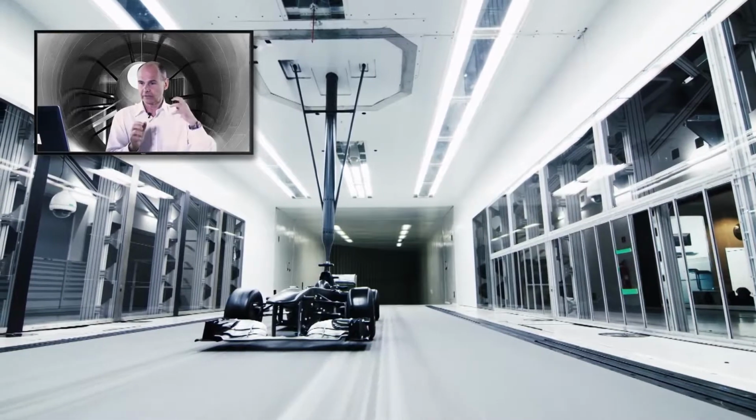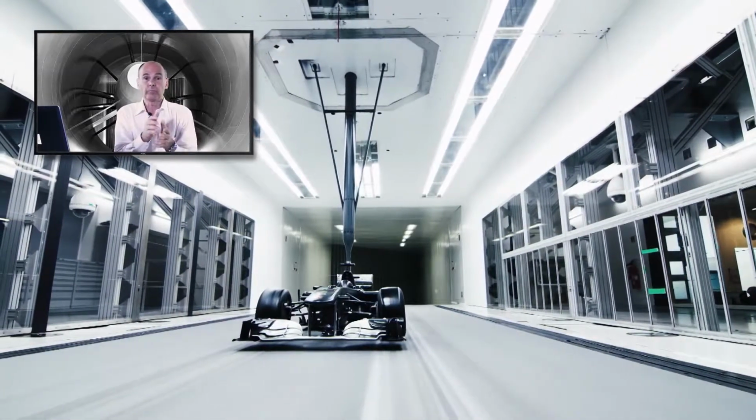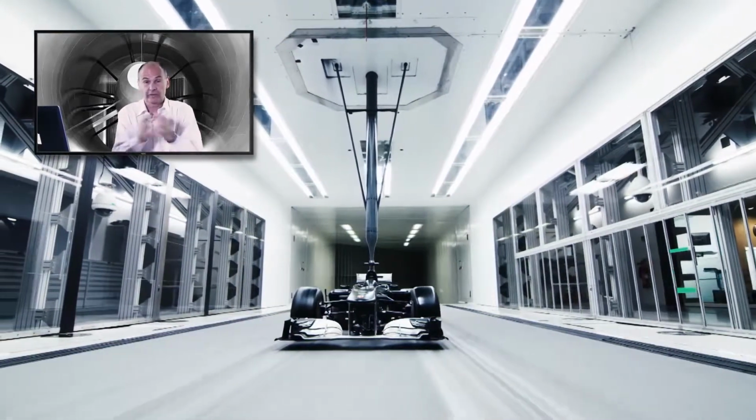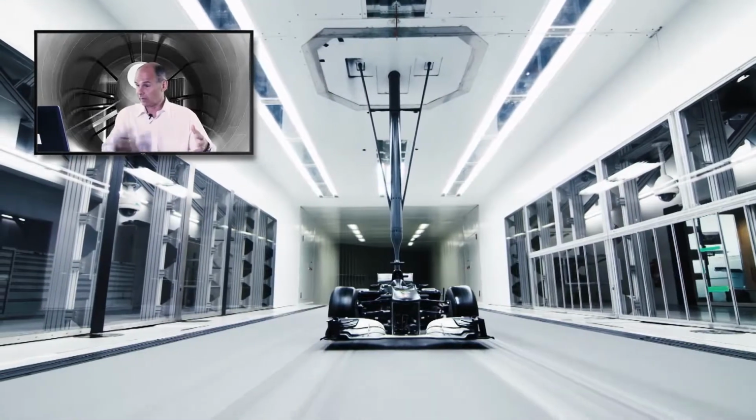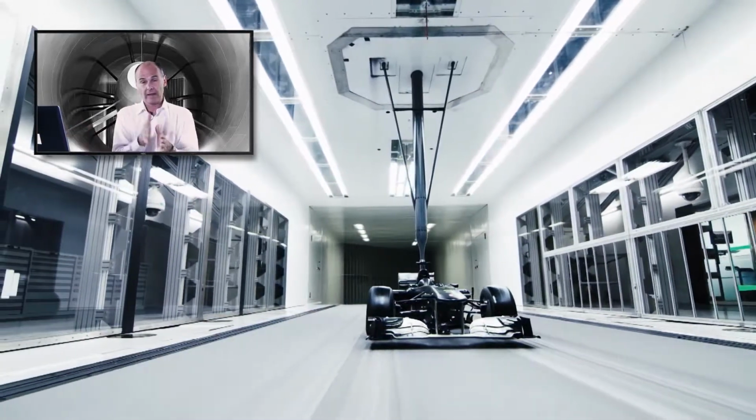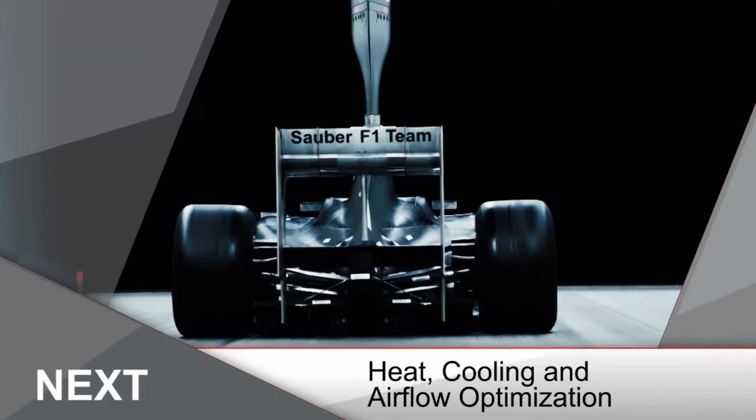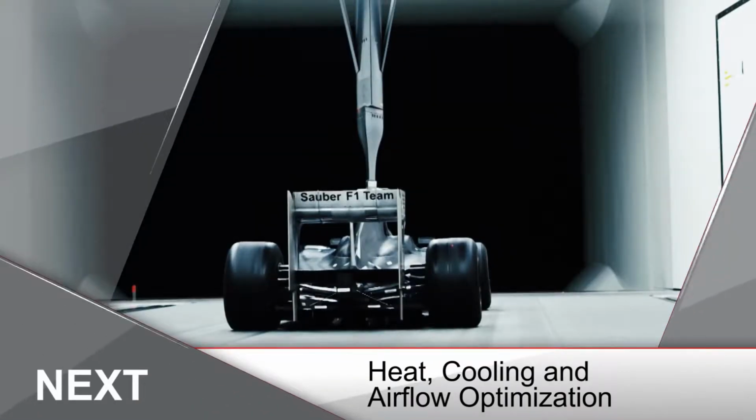If you're driving at full speed, those 3 megawatts effectively generate motion. You call it Brownian motion. It generates excitement between the molecules in the airline, and that energy becomes heat. So we heat the air up as we drive it forward, we have to take that heat out of our airline.